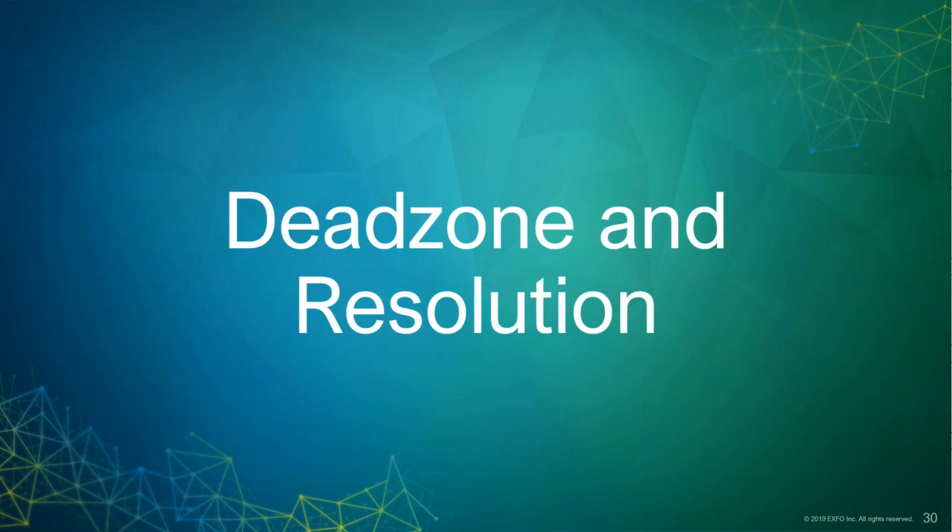In fact, I'll show that to you when I actually manipulate those back and forth, because that really is the key. The key takeaway is ideally you want the shortest possible pulse width in a reasonable amount of time to get all the information that you need. And sometimes that means more than one shot, unfortunately, because the two biggest issues that you run into are going to be dead zone and resolution, right? Dead zone and resolution are directly affected by pulse width.